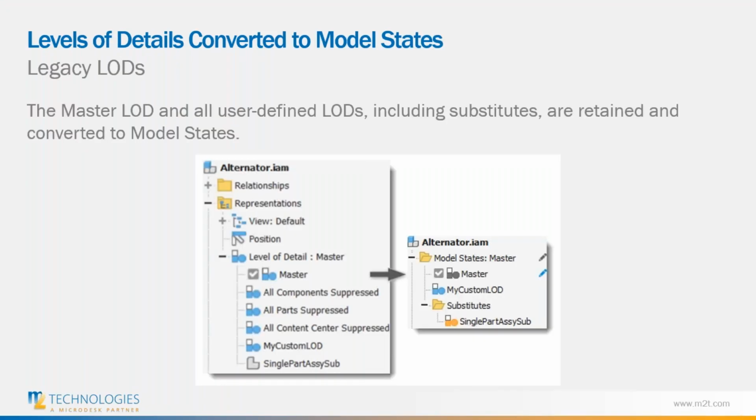Okay, so that's basically the high level overview of what model states are and how you guys can leverage them to improve basically how you manage your data. You could really get away from the use of iParts and iAssemblies and leverage model states to simplify things, make things easier to manage, easier to use. Everything's in a single document file.